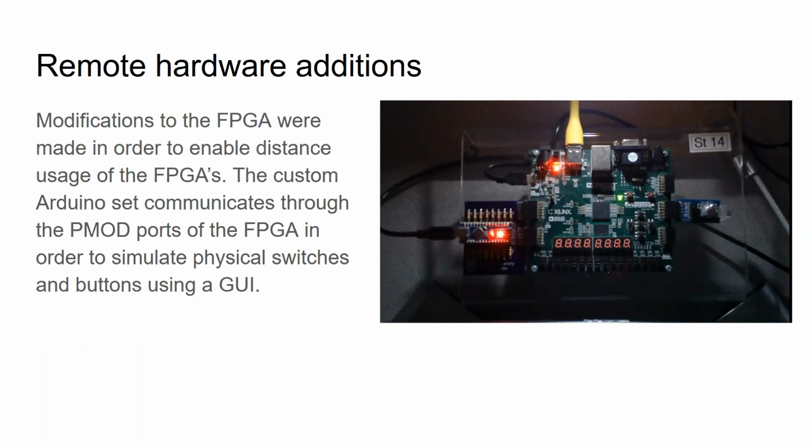Oh, okay. So that's how they've connected it. The reason they've done that is because those are the only IOs on the board. Okay, that makes sense. If they wanted to connect actual pins and keep the same constraints file, they would have to solder cables to the switch points. They'd have to basically mess up the board in order to do that. A bit extreme, I think. So this was probably the better solution. Not to mention the manual work involved in having to do that.